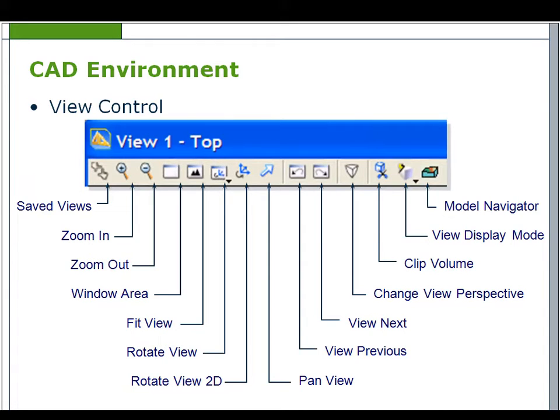The View Control is only available in MX Standalone and MX in Microstation. It appears by default at the top of each view. View Attributes selects, controls and changes the type of elements and graphic attributes in the information displayed in the view. Save Views is used to name, save, delete, import, apply and recall saved views. Saving a view allows you to quickly recall a view with specific attribute settings.